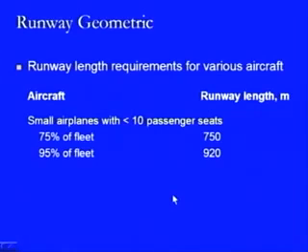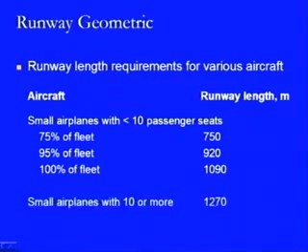That is, we require a little longer length of the runway strip, because here what we are assuming is that there is a queue, and as the number of aircraft increases, at the time when one aircraft is taking off, another starts coming towards the runway strip so as to take position and start taking off, and that is why we require a little longer length so as to have a safety aspect. Then if there is 100% of the fleet being used with the small airplane, the runway length will be 1090 meters, as per ICAO.